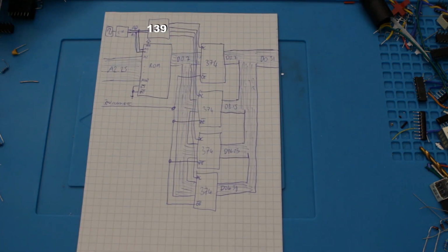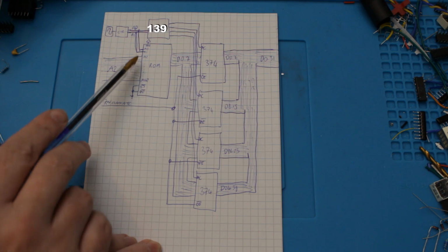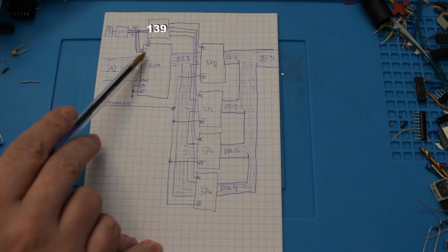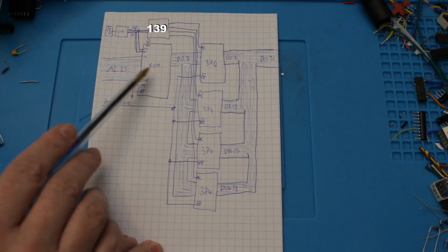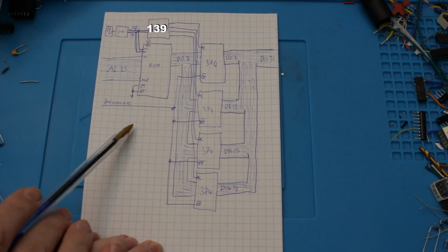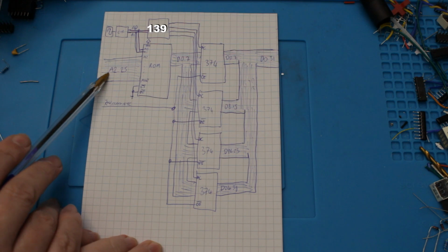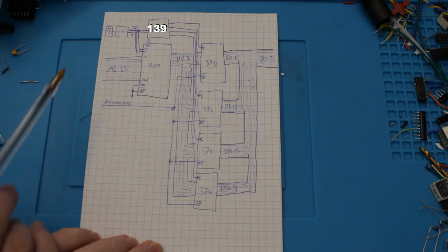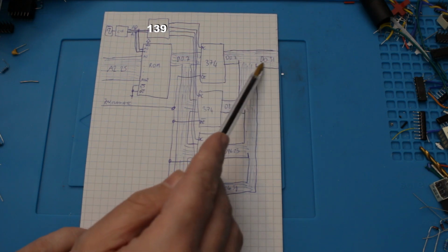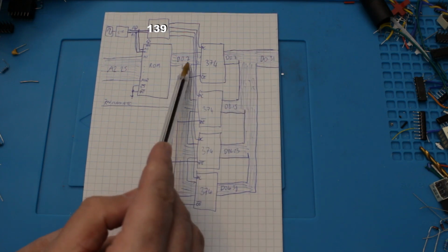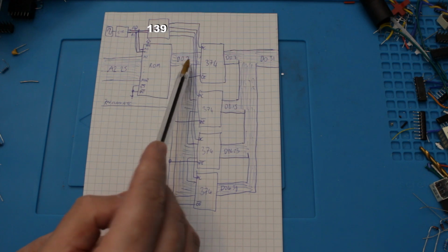So this one seems a likely contender. The idea here is that there's only one ROM chip, and we just write the ROM image with all of the bytes sequential as you'd expect. Nothing fancy going on there. And again, it receives address bus lines 2 through 25. Then, in order to actually fill in the CPU data bus, which is 32 bits wide, from this ROM data bus, which is 8 bits wide,